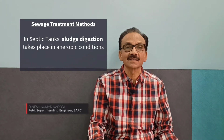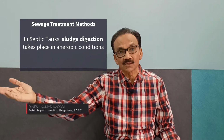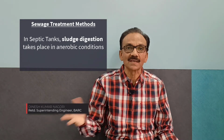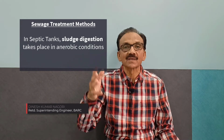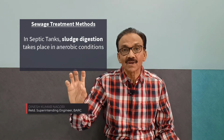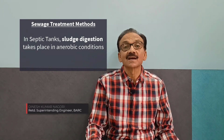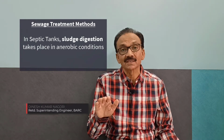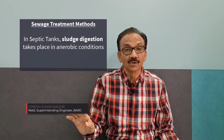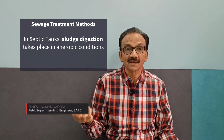Now what happens exactly is, whatever you are putting inside the septic tank, the surplus water should go out from the other end. But generally what happens is, septic tanks are used as a storage tank, because if the inlet and outlet system is not functioning properly, the whole sewage will get accumulated in the septic tank until the tank becomes full and it is not taking anything further. At that time people clean it in 8 to 10 years' time and then remove it. Whereas as per norms, every year or at least every 2 years, the septic tank must be cleaned properly. That too in the presence of qualified people, because nowadays a lot of this we are listening to in newspapers and other places.